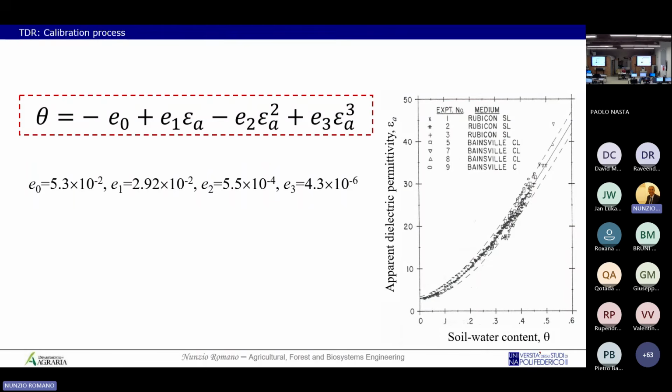So if you are working in the same soil type from the pedological, physical point of view, you can collect the samples in a couple of points just to have the particle size distribution, the bulk density, the oven dry bulk density, to see if things are quite similar, and you can make the calibration only in a couple of locations.